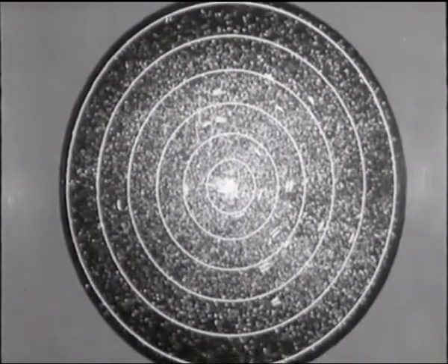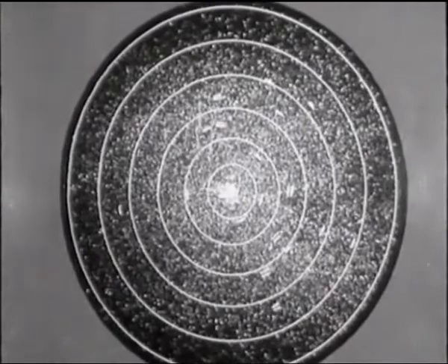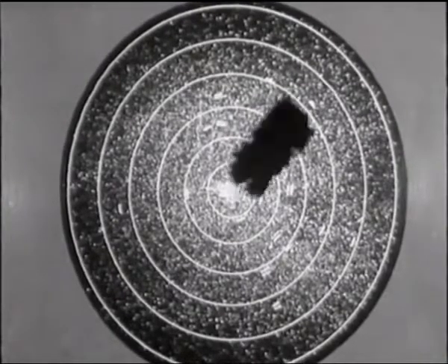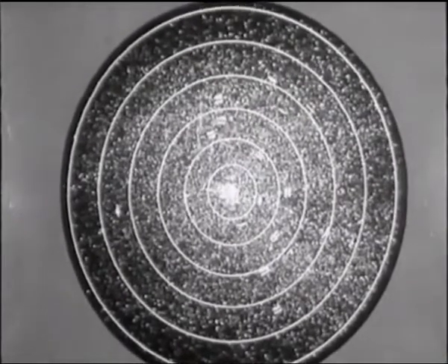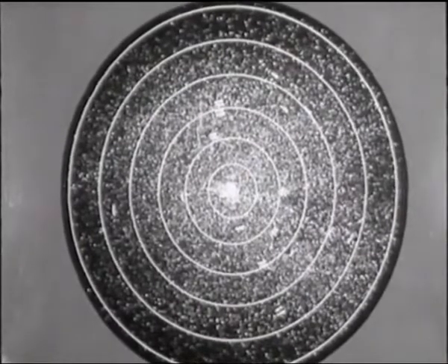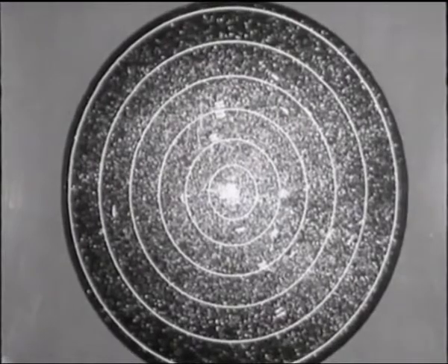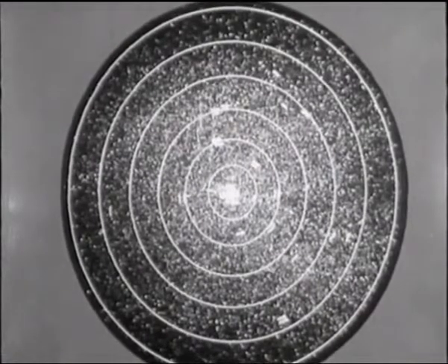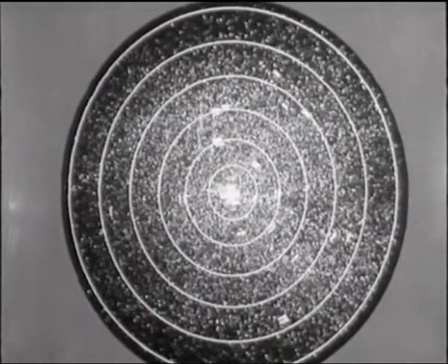In areas of heavy air traffic, a secondary radar display can be very cluttered with the replies of aircraft to other interrogators in the area, which of course are not synchronized with the display in question. This interference is called fruit.